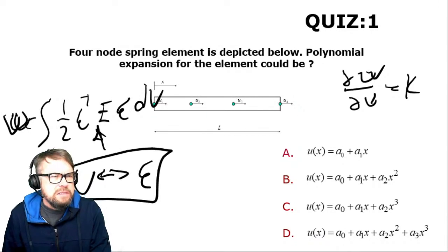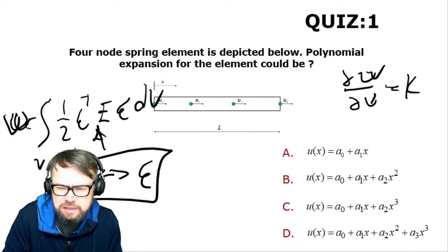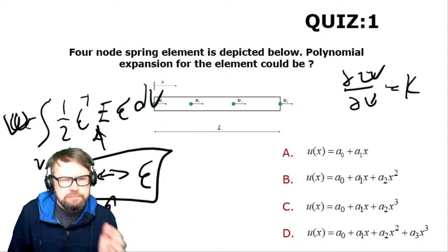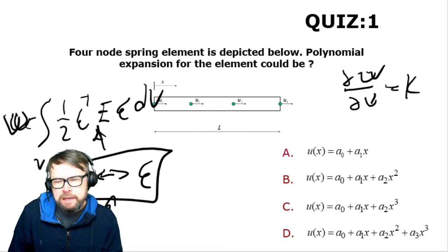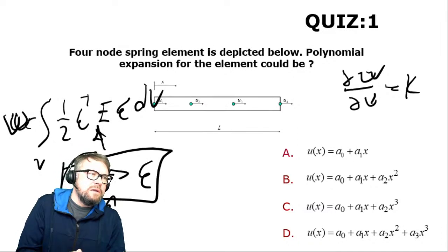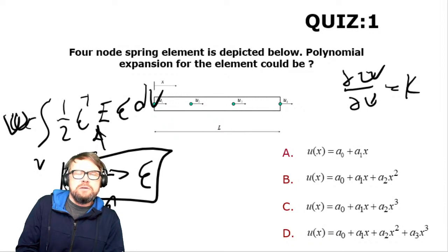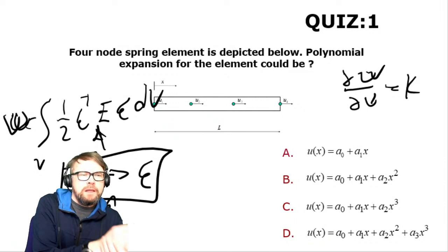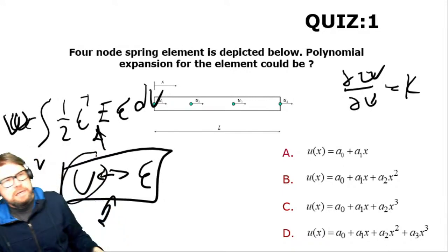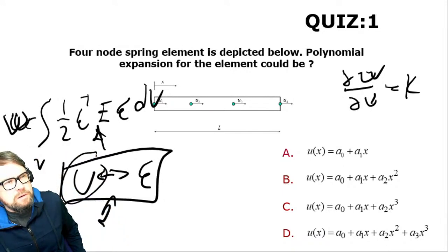And once we have that, then it's very mechanical. Actually, these two are already very mechanical. So the only thing you need to get in finite element modeling is this U. And again, how can you get the U? You need to identify the number of degrees of freedom. And once you know the number of degrees of freedom, you express them using polynomial expansion. That's it.